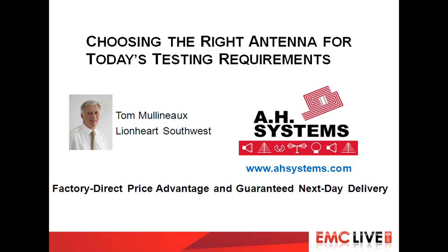And so today's talk clearly is on choosing the right antenna for today's testing requirements. And today's testing requirements usually mean high frequency tests. There are a couple of things that come into play with high frequency tests, and that's particularly the beam width of the antenna. That is, if you're illuminating a calibration plane, then you get bending within that plane, and the external calibration points will see less of a field than the very center of the calibration plane.